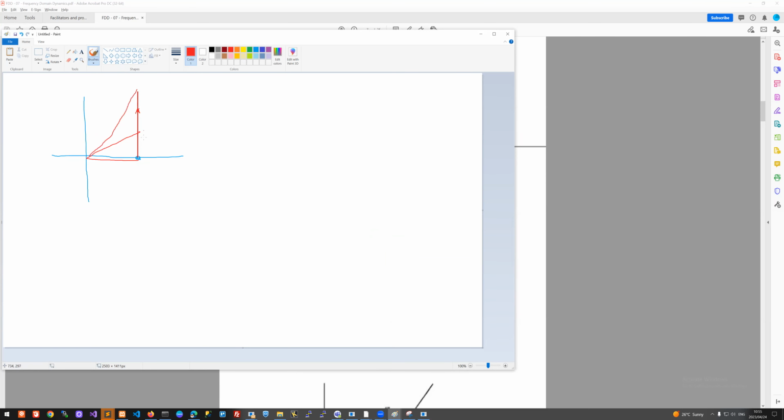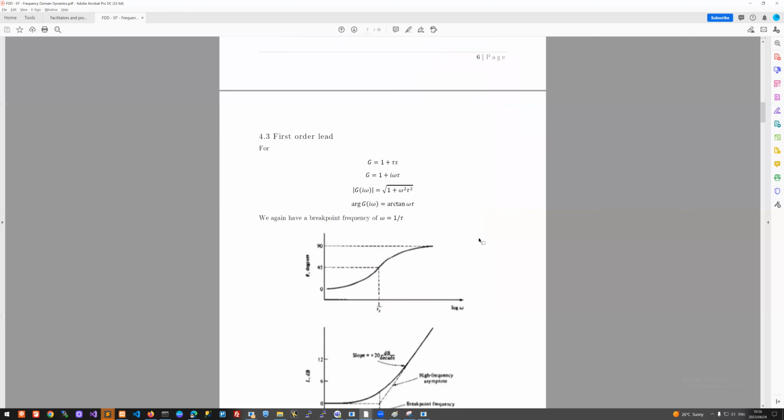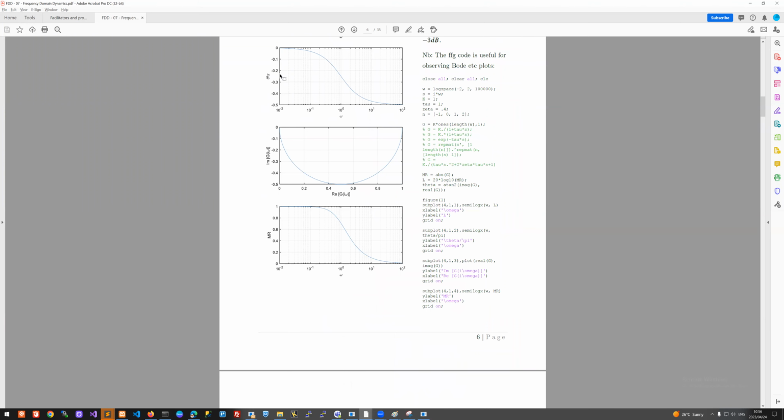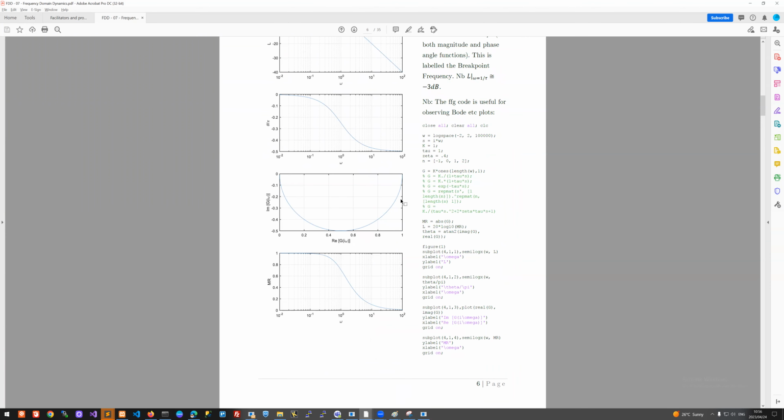And we can imagine when this point moves infinitely far away, the situation looks much more like this, that there is a little 1 here, but we've moved so far up here that in essence, we are sitting on the imaginary axis. And so the angle has gone from 0 to plus 90 degrees now. And so there's a nice little symmetry that comes up here. You get your angle going from 0 to plus 90. Remember, in the previous case, the angle went from 0 to minus 90.